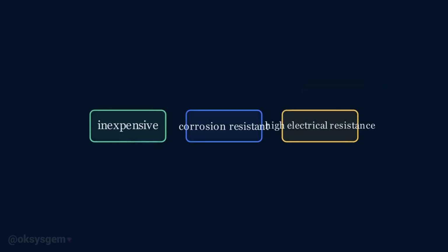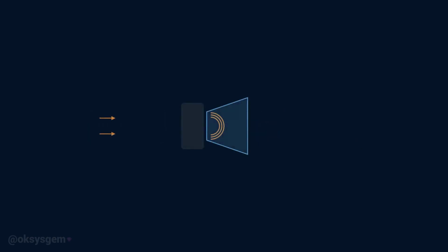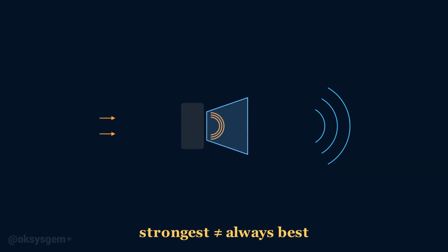They are inexpensive, resist corrosion reasonably well, and can be manufactured in enormous quantities. They also have relatively high electrical resistance, which can reduce unwanted electrical currents when they are used around changing magnetic fields. This makes ferrite useful in electric motors and loudspeakers. Inside a speaker, for example, a permanent ferrite magnet interacts with a coil carrying and changing electric current. The resulting electromagnetic force moves the speaker cone backward and forward, transforming an electrical signal into sound.